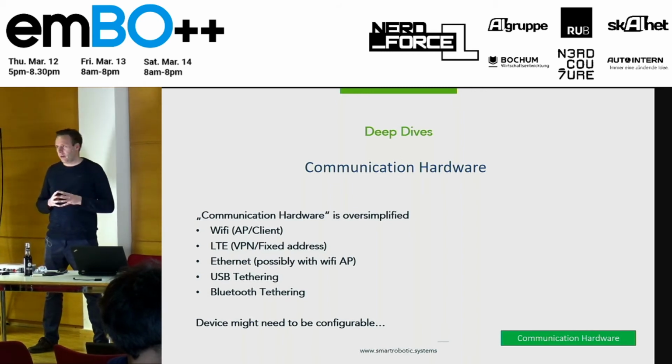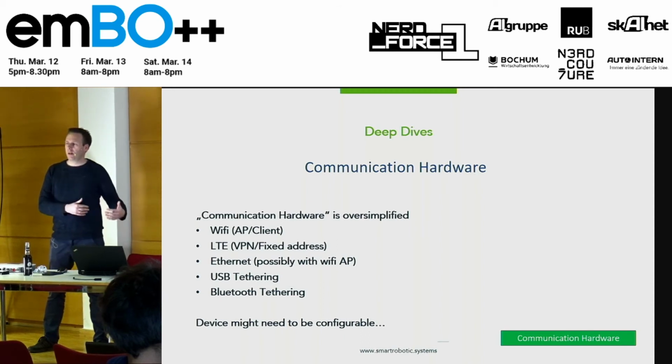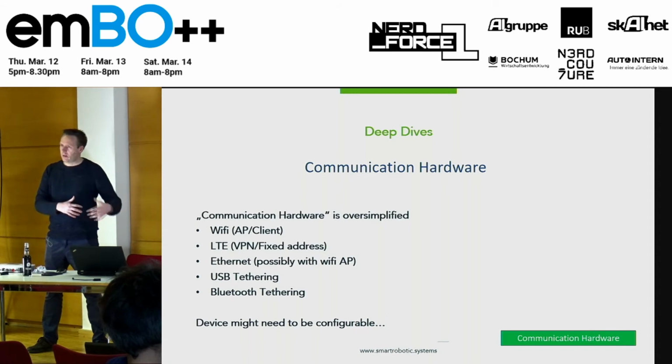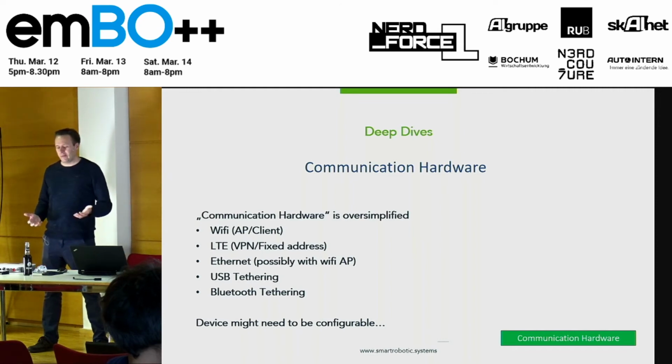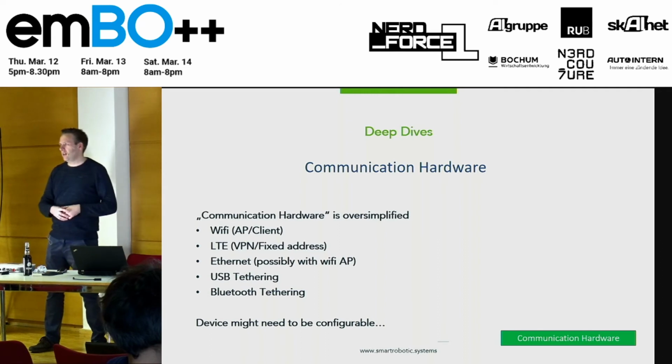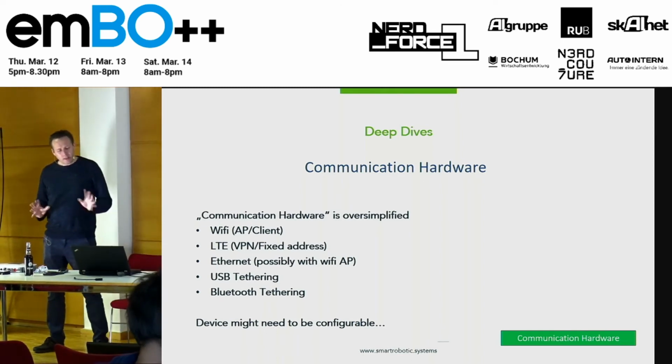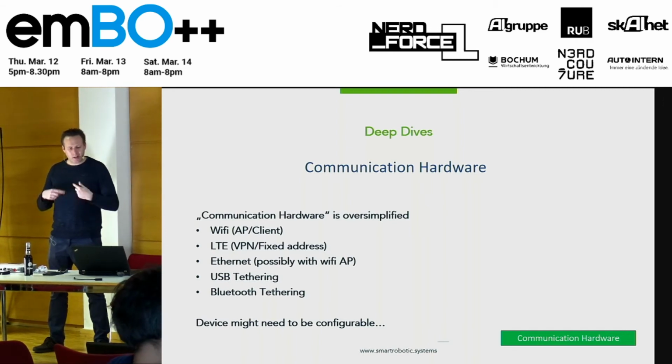when you're using Wi-Fi, you have to look at whether your embedded device goes into a Wi-Fi network that is on the site where you deploy it, or it opens up its own access point, and then your mobile phone or whatever can only connect with your device and not with other devices at the same time, mostly. So this needs some thinking for your specific use case.